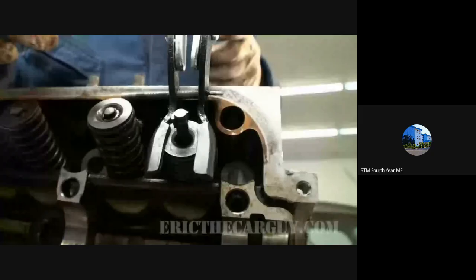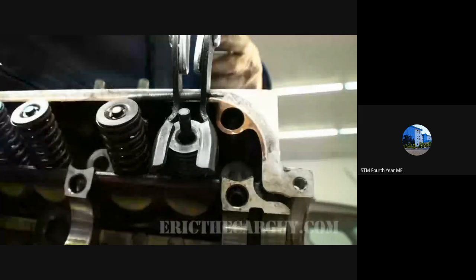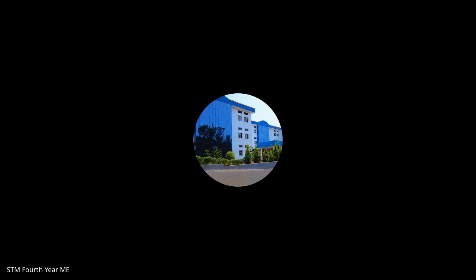There is a magnetic tip point, and he removed the lock nut. And when we release the compression in the valve spring compressor, there is a releasing. See, the spring is removed from the valve. Take the spring and valve cap. That's the valve cap that is holding. And then we can remove the valve also. So that is the lock nut, and that is the inlet valve. That will be the bigger valve. So it is the inlet valve.